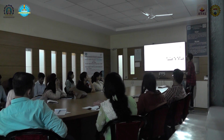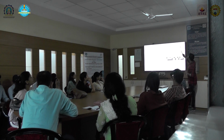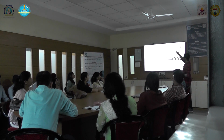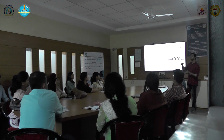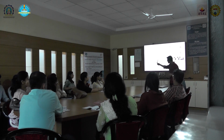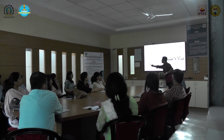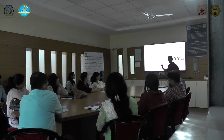We write constraints on the input signals to restrict them. We have rec, done 1, busy 1, done 2 and busy 2 as our input signals. So we will write a constraint for the rec signal. We know that rec, or a request, can only be sent when the interface is free, that is, not busy. So rec will be sent only if the interface is not busy. This is an expression, and we make it into an assumption by writing assume property. The rest are names, the name of the property. Here we just write assume, block dependency, and the expression. Any questions?